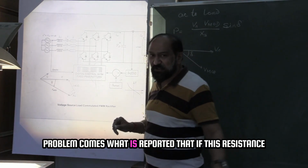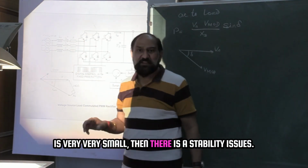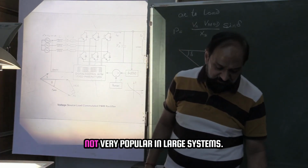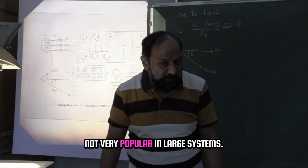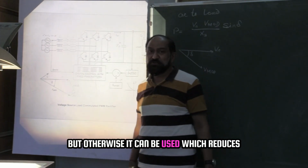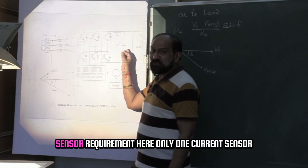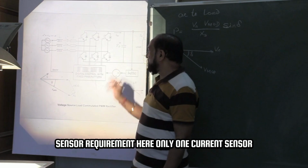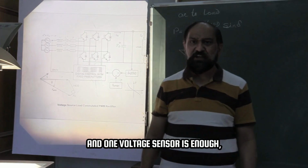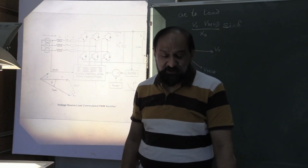The problem is, it is reported that if this resistance is very small, then there are stability issues, and that's why this method is not very popular in large systems. But otherwise it can be used, which reduces the current sensor requirement here, and reduces the voltage sensor requirement here. Only one current sensor and one voltage sensor is enough, because the rest of them can be shifted by 120 degrees.